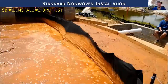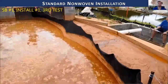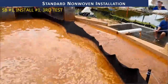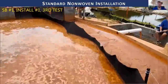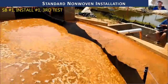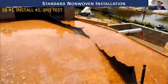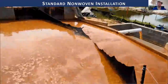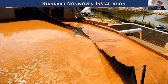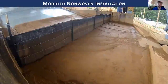So just to give you an idea of what a standard silt fence performs, this is how ALDOT used to have their standard silt fence installations designed. It was a geotextile installed with 0.95 pound per foot T-posts spaced 10 feet. And after three simulated storm events, we realized that the geotextile fence fails because of all the stormwater impoundment. Essentially the fence is not strong enough to hold back all of this sediment-laden water, so you have sediment-laden discharge.